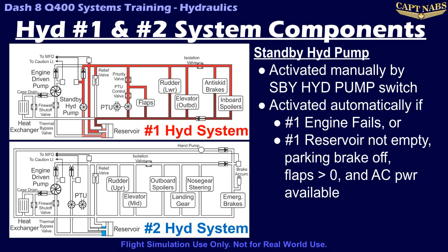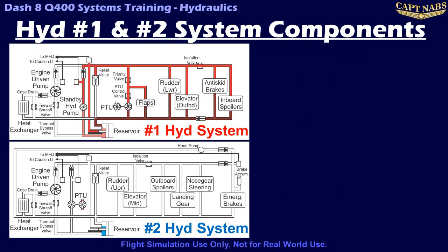However, relying on the automated system causes more wear and tear on the pump and the related wiring, as the pump will cycle off and on each time the parking brake is set and released during taxi. This is why the manual switch is used to force the pump on for the entire takeoff, landing, and taxiing period.